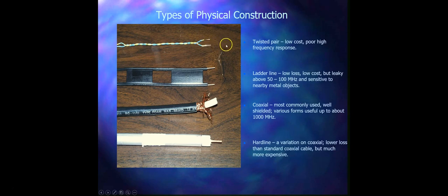These twisted wires are closely together, which improves the shielding ability to reject any unwanted signal. Twisted wire also increases high frequency losses because the capacitance between the two wires increases. Above a few megahertz, a twisted pair of wires is not very useful for a transmission line, and it becomes very lossy. Therefore it is not good for radio frequency transmission lines.